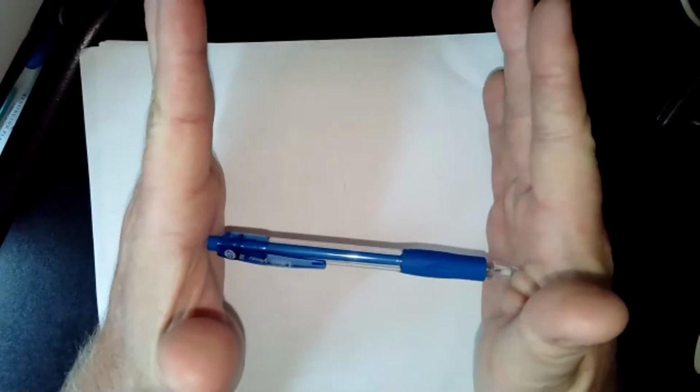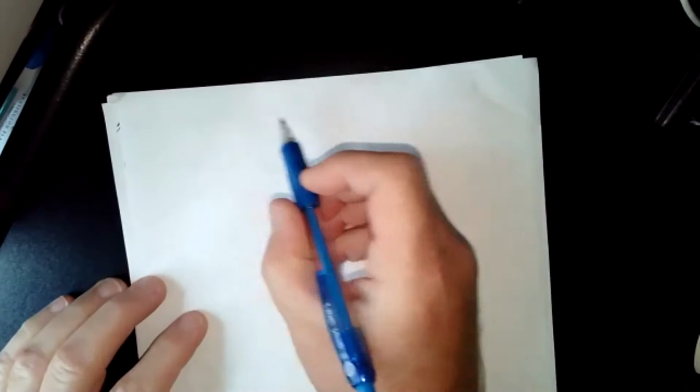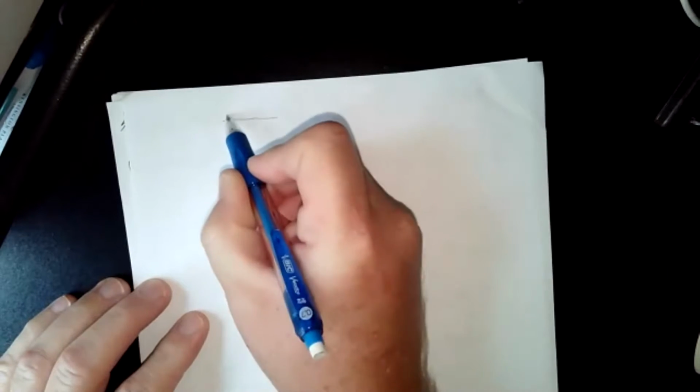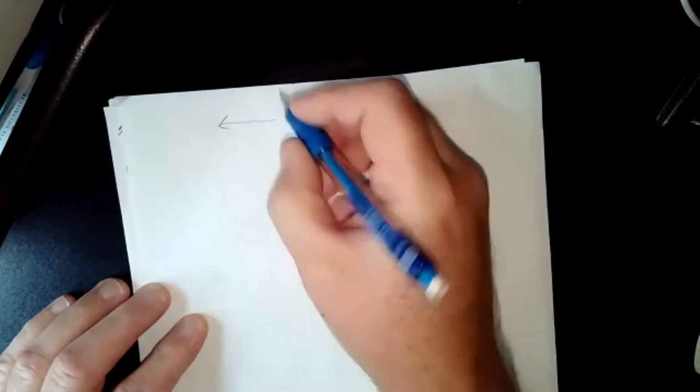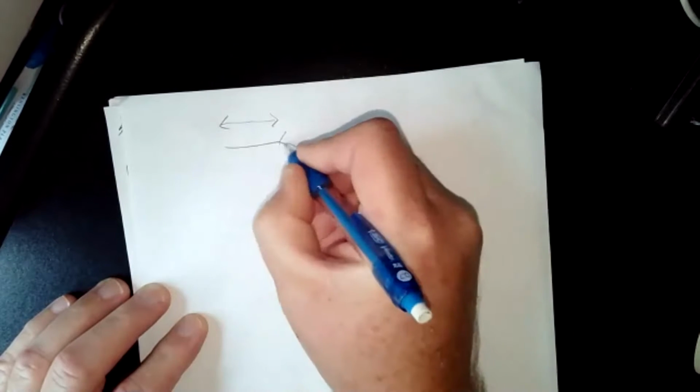Think of it like a pencil. If I push in on the pencil, what do you feel? You feel the pencil pushing out, so you're compressing the pencil. Just like in the drawing you have, if it's in compression, the arrows are always pointing in.